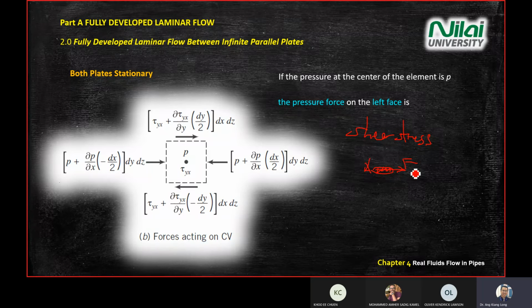Means this combination, you get shear stress. So again, you're taking stress. Shear stress means that you take force divided by area. Only the force direction that is parallel to the area, you get shear stress. It is this one, right? So you have a positive and negative here. So you understand why you get dy divided by 2?